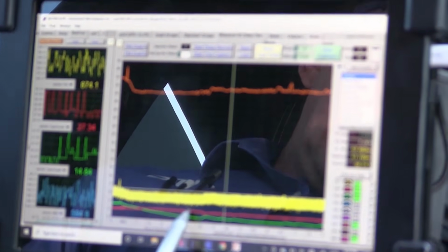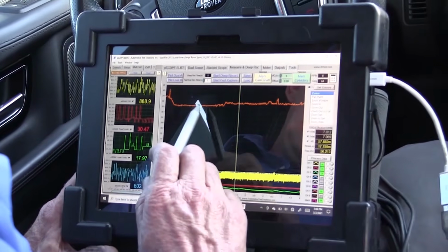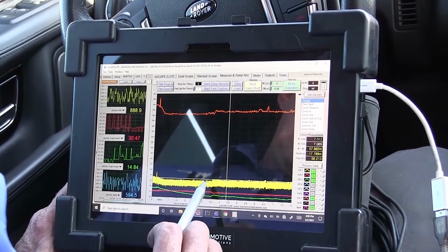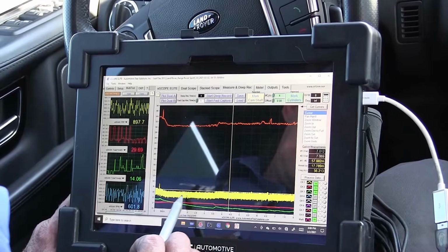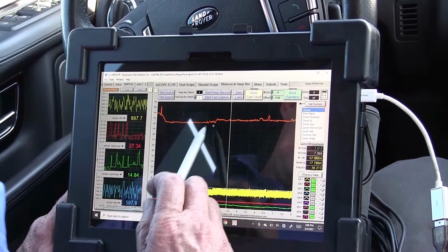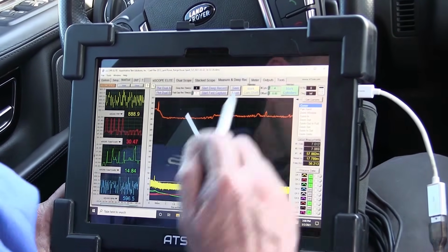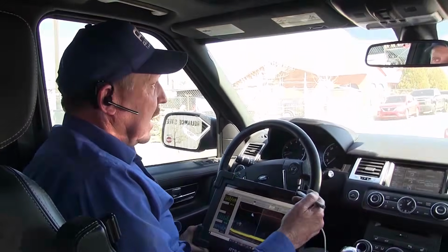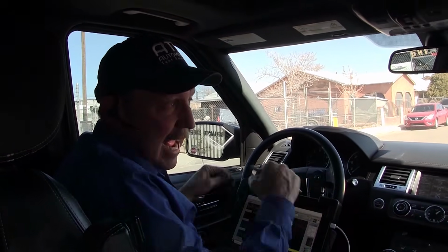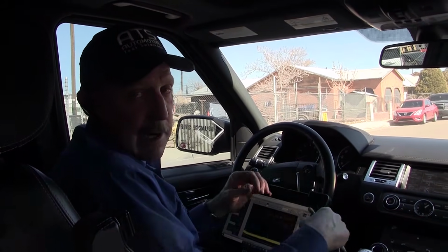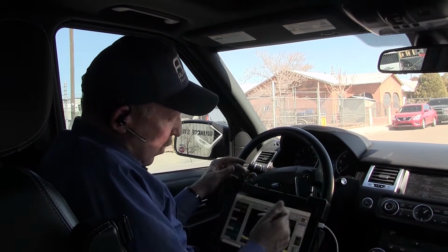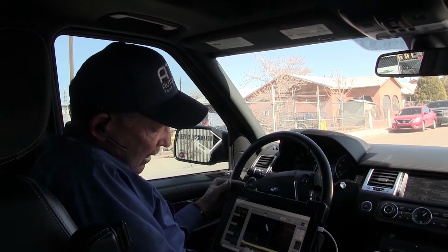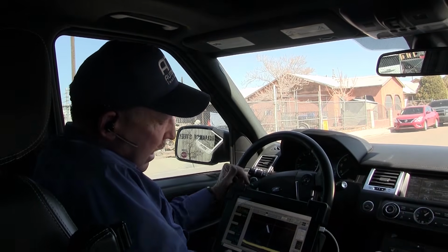Now, I could have maintained the pressure and made it steady if I would have increased the duty cycle to the pump, but I would have seen the current coming up. And I don't see that current coming up, nor did the duty cycle try to drive it. So what that's telling me, guys, is this pump is staying loaded with fuel pressure and it's not cavitating. It's not getting air to where all of a sudden I'm giving this air to the high side.